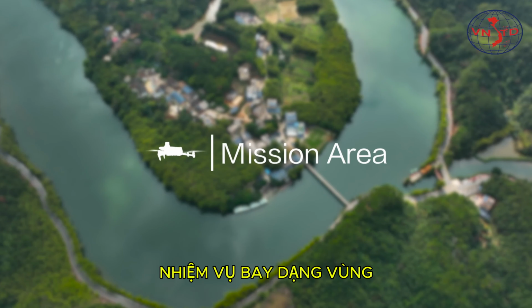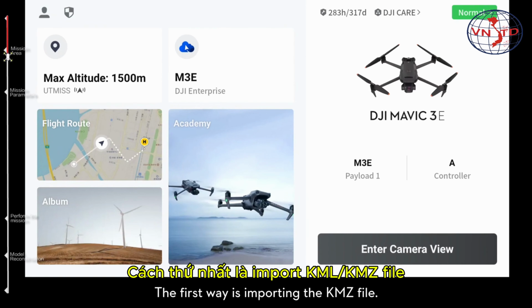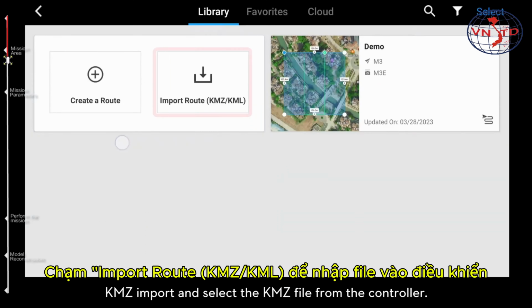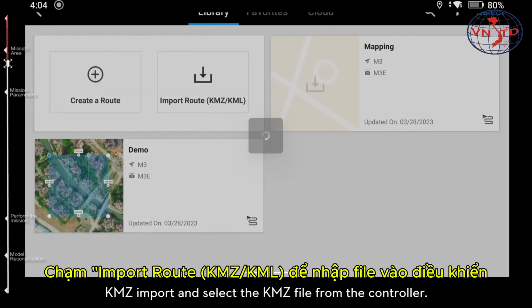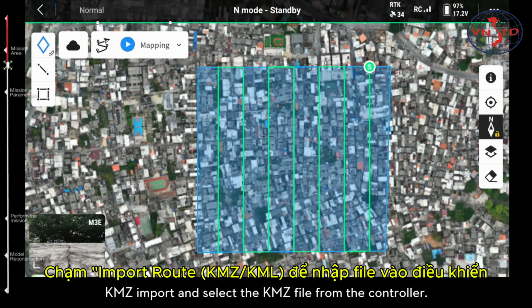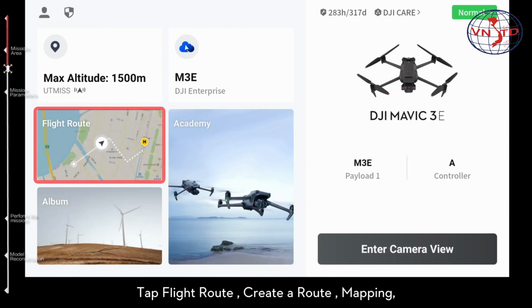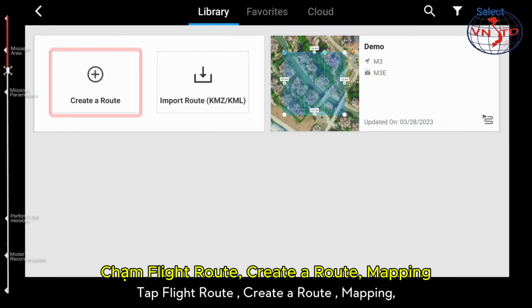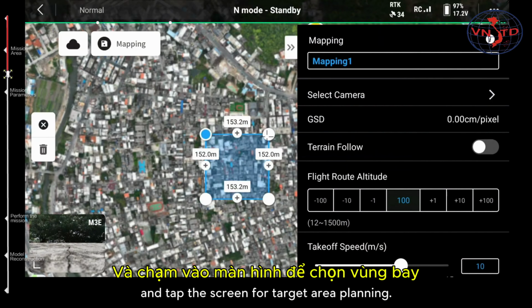Mission area. There are two ways to create mission areas. The first way is importing the KMZ file. Tap Flight Route KMZ Import and select the KMZ file from the controller. The second way is creating the area manually. Tap Flight Route, Create a Route, Mapping, and tap the screen for target area planning.